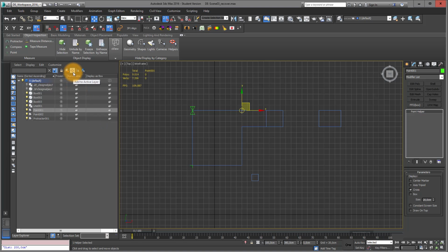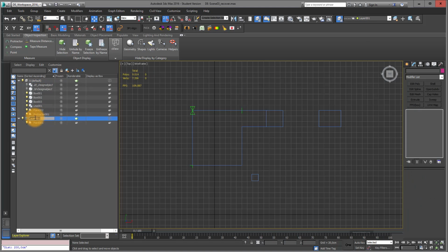And if I go on to this plus symbol, and I had selected one, then I go onto this menu point, Create Layer, and I can call this layer helpers. I select with my shift key my helper points and move them on top of the layer symbol, and then you can see that you can put them into the layers.